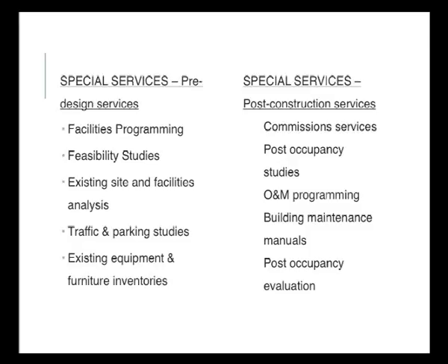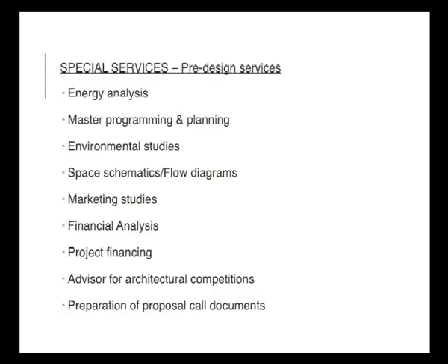The special services, pre-design services and post-construction services, can be divided this way. So, the pre-design will be facilities programming and feasibility studies. Yes, we need to have a feasibility study before we perform any design at any site. So, existing site and facility analysis, traffic and parking studies, existing equipment and furniture inventories. We need to calculate the estimated amount of furniture for the future. This will help cut short the furniture expenses. Energy analysis, master programming and planning, environmental studies, space schematics, flow diagrams, marketing studies, financial analysis, project financing, advisor for architectural. This is what the pre-design service involves.